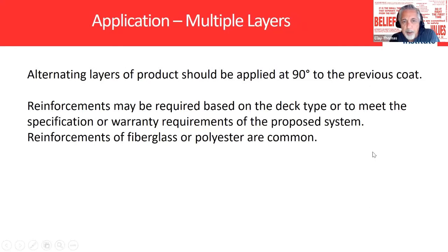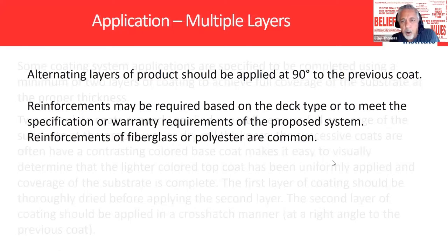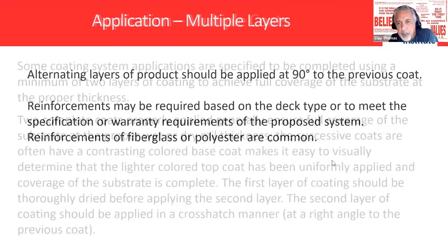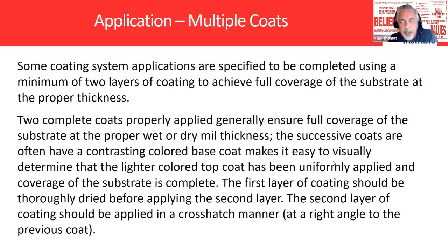Reinforcements may be required based on the deck type or to meet the specific warranty requirements of the proposed system. And again, we talked about reinforcements of fiberglass or polyester mat. Also, with multiple coats, one of the things you've got to be concerned with is recoat windows. Frank, you want to talk to recoat windows a little bit? You're dealing with that at the courthouse.